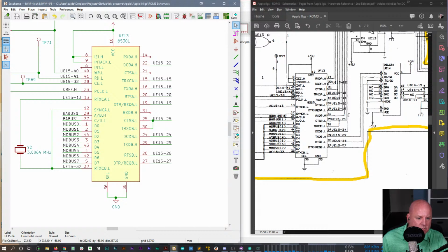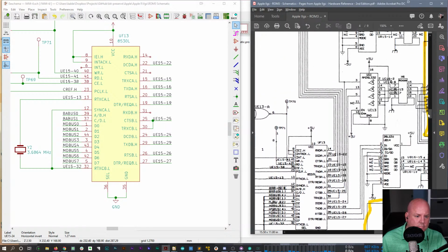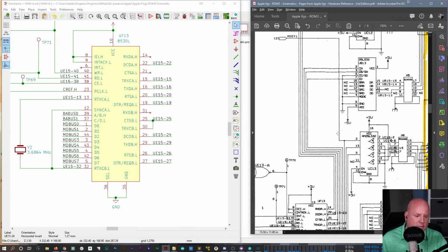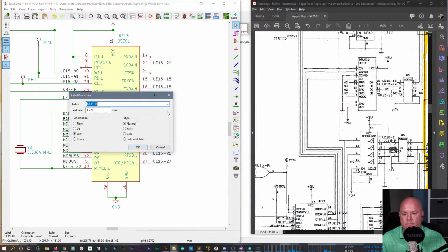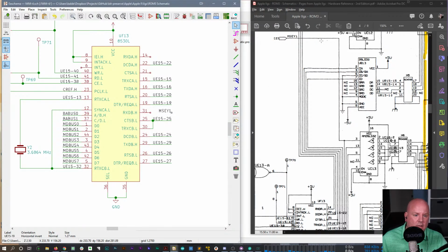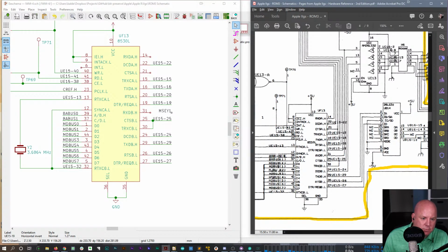So it's 1, 2, 3 over from, right? 1, 2, 3. Okay, so as long as you follow this bundle, it's the third wire from the right. So it breaks here, so it goes 1, 2, 3. So it's going to this pin, pin 3. Oh, that's convenient. And then that comes up to nothing else except for MSY1. So I'm going to name this one MSEY1. And let's go all the way down. So we'll add a label to it over here, and I'll probably put the global label right there. And then just carefully follow this one.